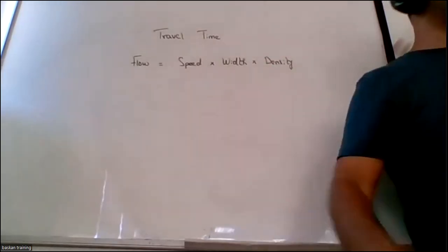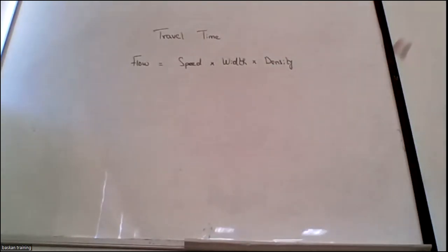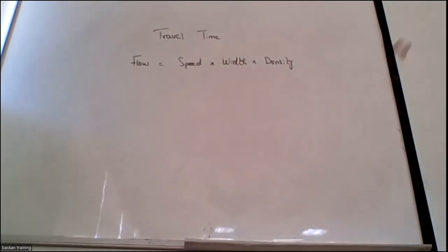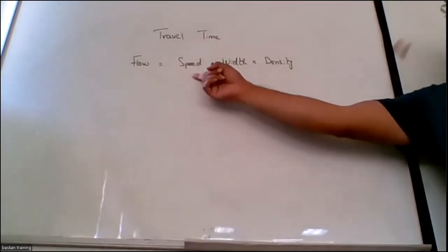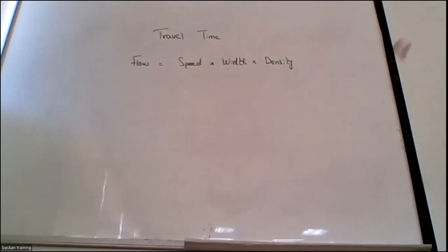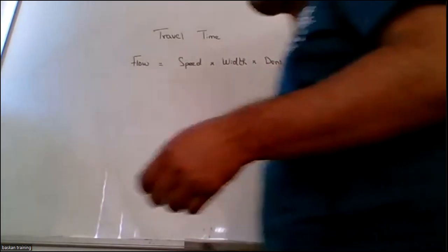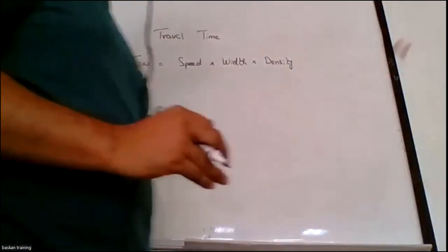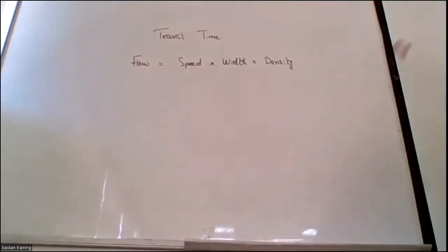So flow of a person, movement, depends on speed, density, and flow. People movement totally depends on flow, speed, and density, and for means of egress, width will be included. Movement depends on flow, the number of people per second, the speed at which they are traveling, and the occupancy they are covering. Each terminology here has a unit. Density, for example, is people per square meter.